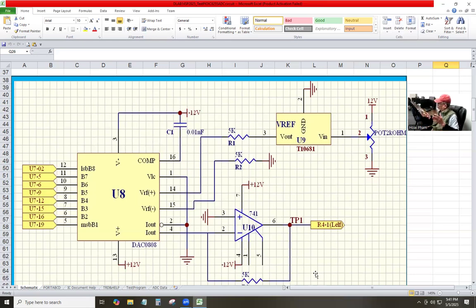The thing is, when you try to measure the current, you have to break the circuitry to let the current go through the meter. That's not allowed, even here or at work. So that's why we have to add in the U10.